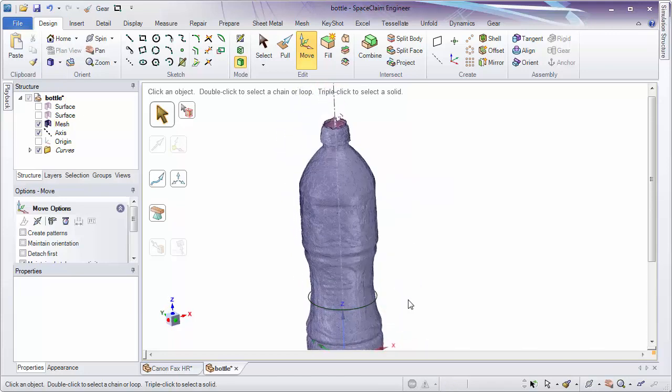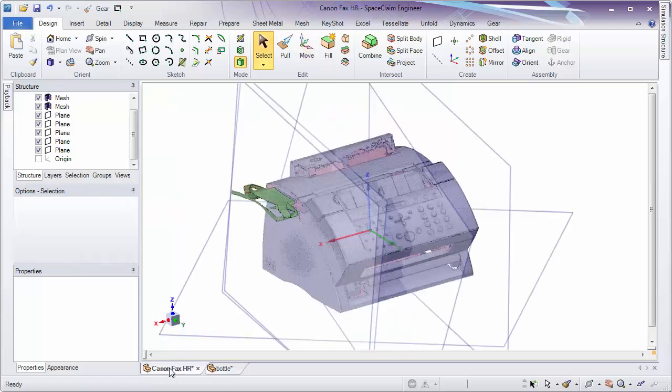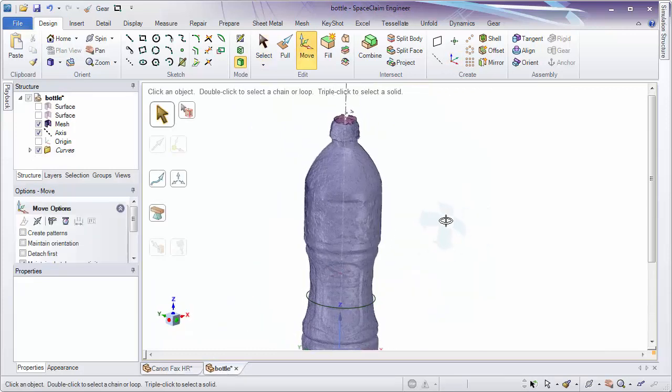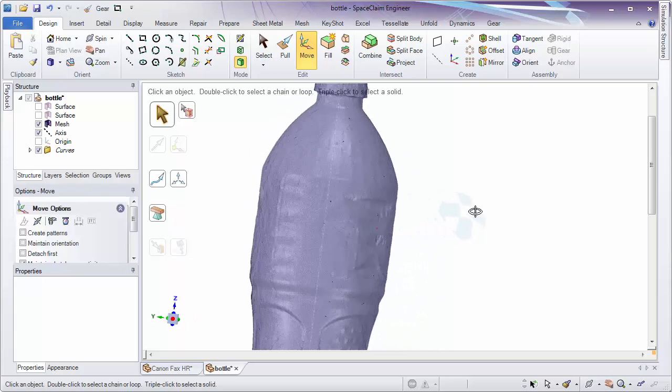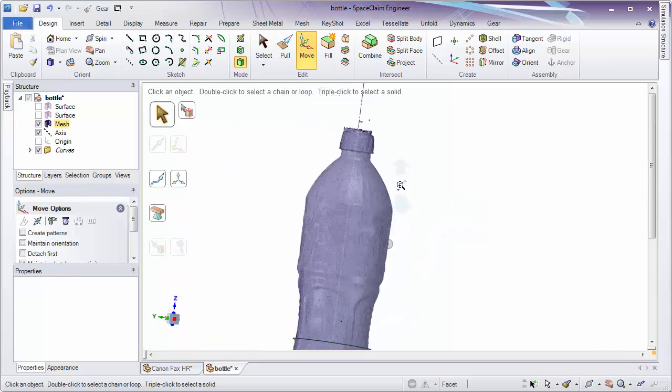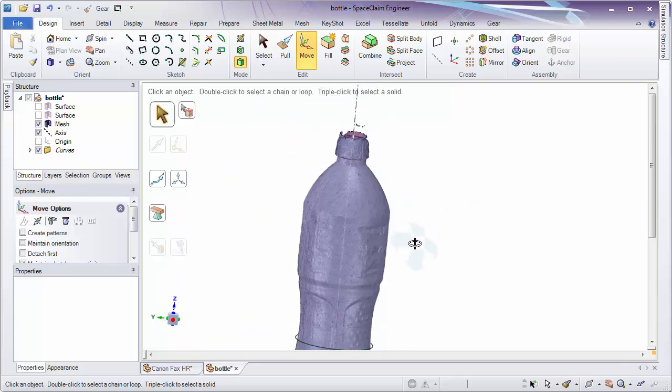So this is the workflow in terms of orienting prismatic parts that have nice planar faces or cylindrical faces. Also, when we don't have that luxury and we have to insert in a local origin, as well as something that is a little deformed and we want to find some good data instead of trying to sample all of the data that's in here, because some of this warpage would make the center line skewed a little bit.